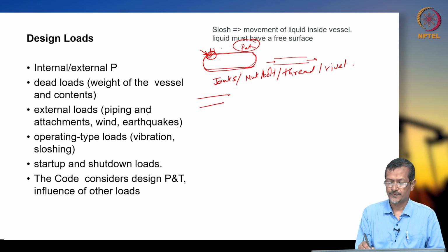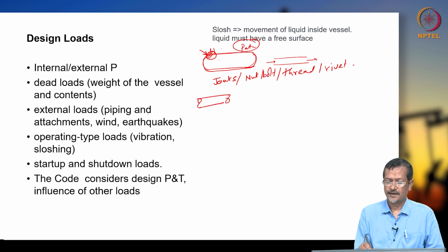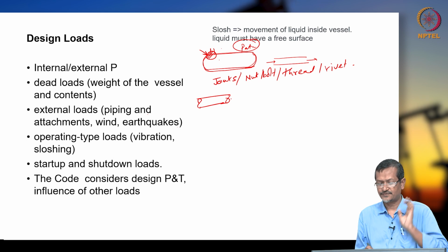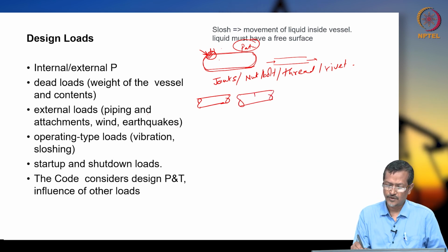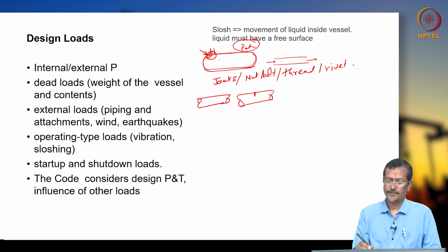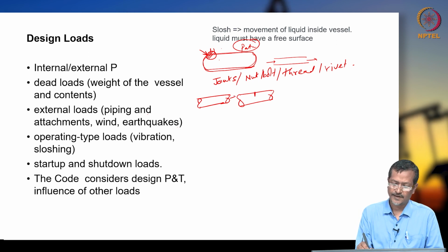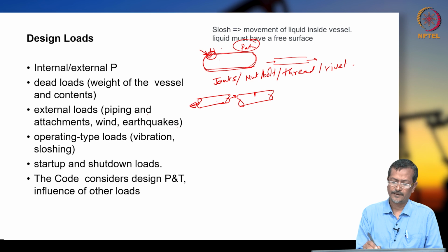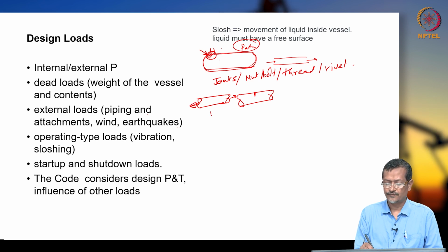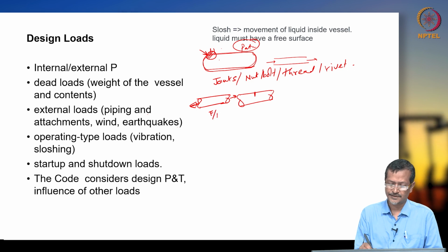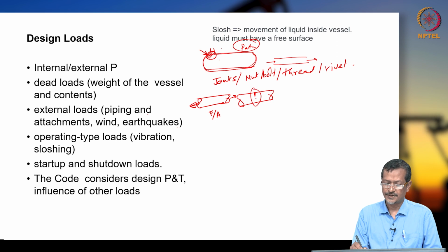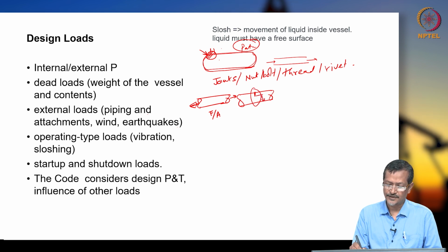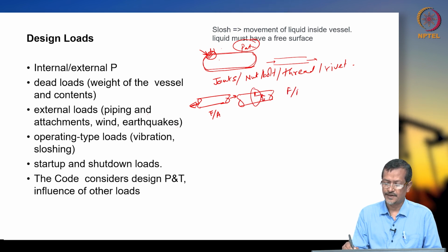I have one rod, okay, like this, and the rod is very smoothly designed, that's fine. Now because of mishandling, you get some small crack. So what will happen if I apply, let's say, a tensile load on this rod? Stress will be generated like this, F by A, right? Force you are applying, area is there. But when a notch is there, the actual area is reduced. So F by A dash.